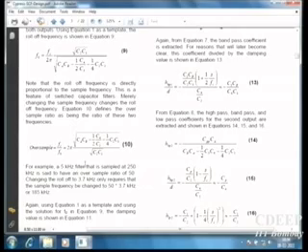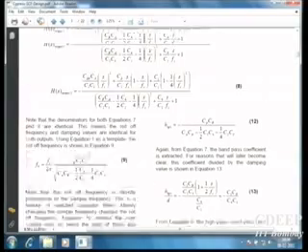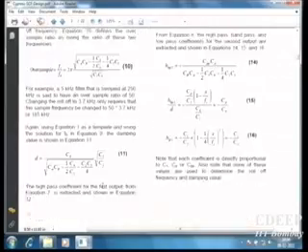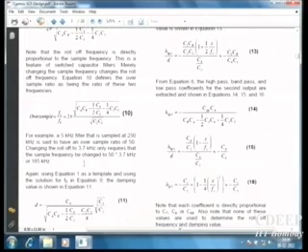And 5 kilohertz depends on what F0 is, whether it is roll off or minus 3 dB frequency or whatever they have designed. Then suppose you want to change the roll off of the filter and you don't change the capacitors, then this means that your sampling frequency also should be scaled by the same value.